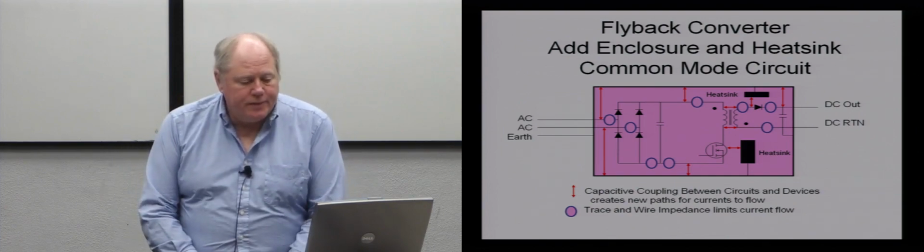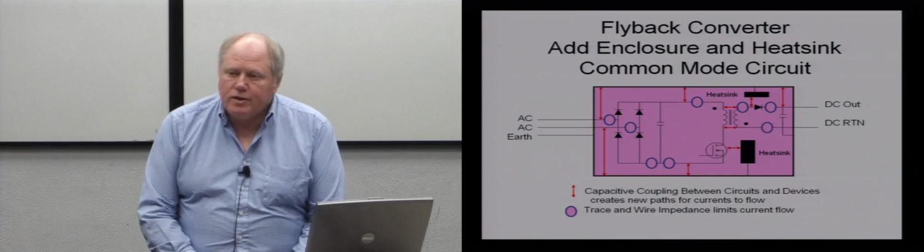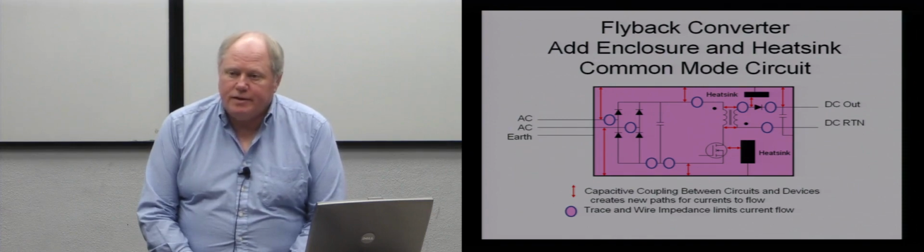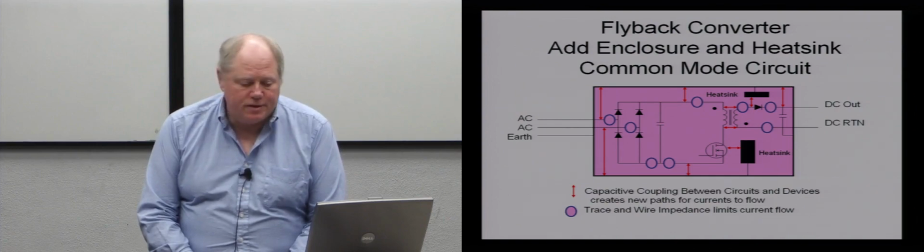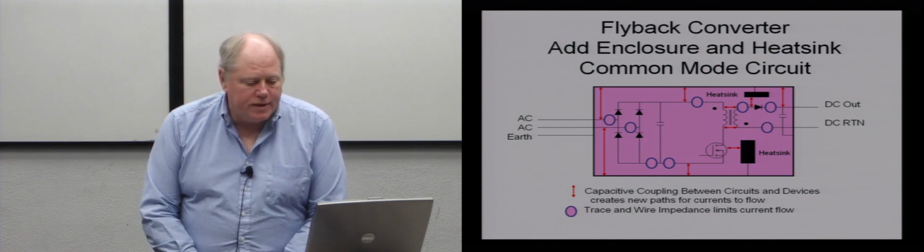So there's going to be a capacitance there to that heat sink, and that's going to bring currents that, every time that FET switches, are going to go into the heat sink. The heat sink has to be safe for people to touch, so you're going to want to ground it. Or if you don't ground it, it's going to radiate. Either way, it's going to be a noise source. It's either going to be conducting current if it's grounded, or radiating an electric field if it's not grounded.